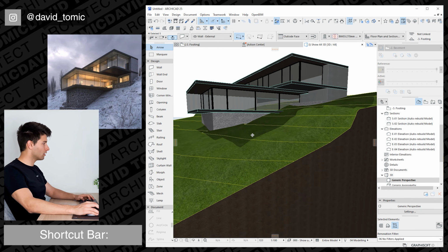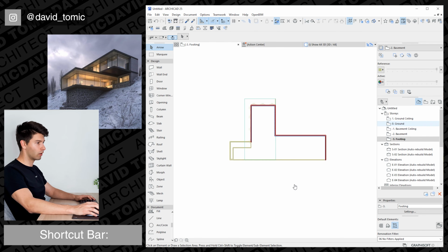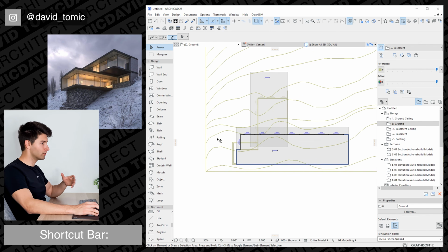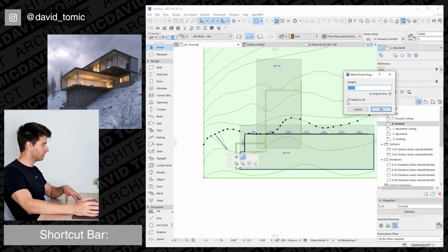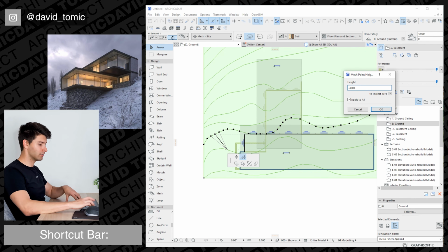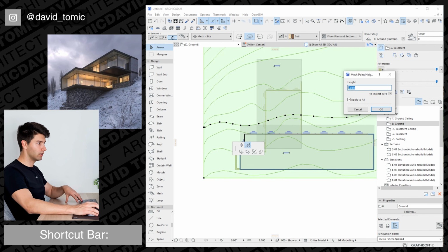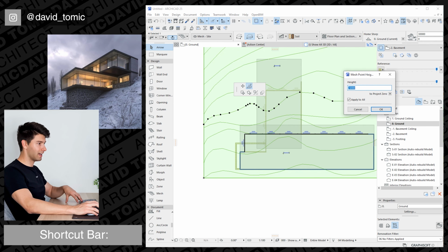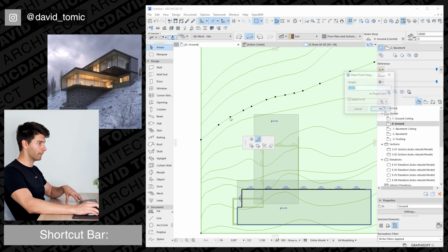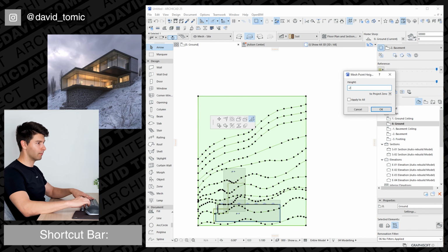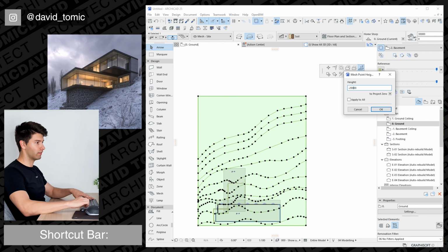And then all of these contour lines aren't dropping fast enough in my opinion. So we're going to come back to our actual ground story and we're going to start adjusting them so they drop significantly quicker. So this line over here, if we click on one of those nodes and edit the mesh, it's at about 3 meters. So let's drop that to 4 and then continue to drop this 2 meters at a time. So this is going to be -6, -8, -10, -12, and I'm going to repeat that till we get to the bottom. Now that bottom line is -20, so I'm going to make both of these -22 so that it continues to fall away instead of coming all the way up.